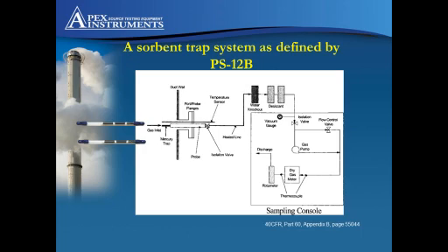This image is taken directly from page 55044 in Appendix B, Part 60, showing the functionality of a sorbent trap monitoring system. We have added the sorbent traps here on the picture just for a point of reference on the system itself. Chris will speak further on how the system works, but to give everyone a basic overview, sample gas is pulled through a set of traps at the end of the probe where the mercury is collected on carbon media within the traps.